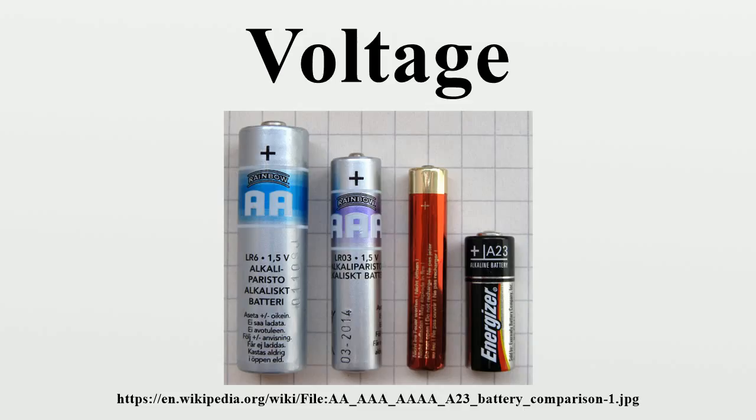Hydraulic analogy. A simple analogy for an electric circuit is water flowing in a closed circuit of pipework driven by a mechanical pump. This can be called a water circuit. Potential difference between 2 points corresponds to the pressure difference between 2 points. If the pump creates a pressure difference between 2 points, then water flowing from one point to the other will be able to do work, such as driving a turbine.